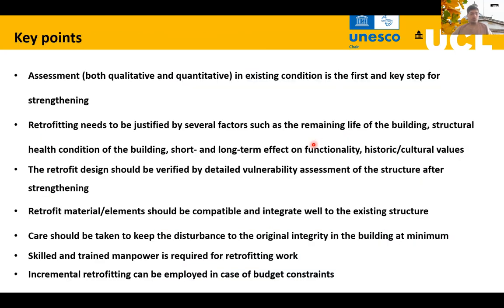These are some of the key points. So that's just a summary of what we discussed. The assessment, both qualitative and quantitative, to identify the deficiencies in the existing condition is very important for designing any strengthening. Retrofitting needs to be justified by several factors, such as remaining life of building. If the building is expected to have 5 more years of its life, then there is no point in retrofitting.